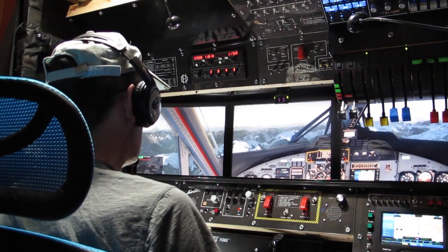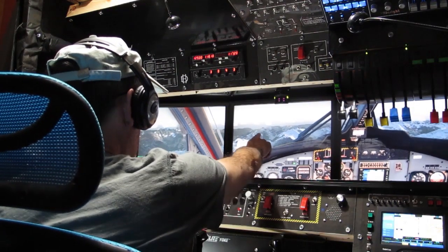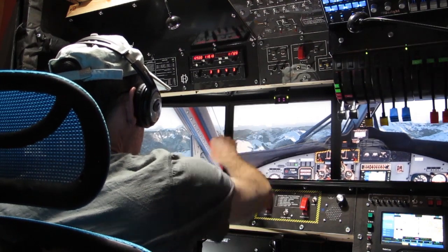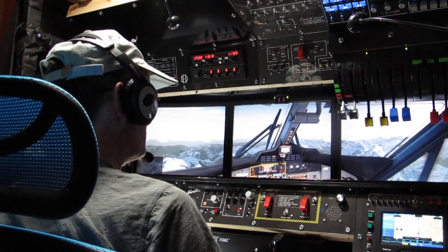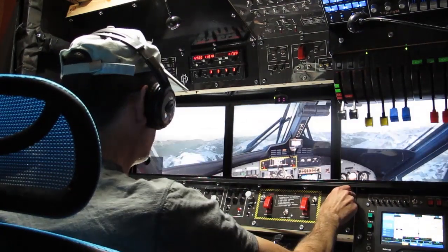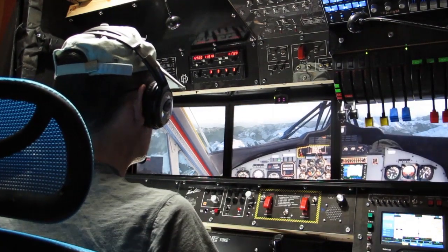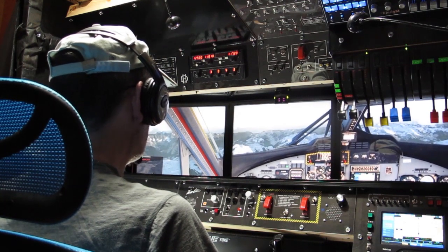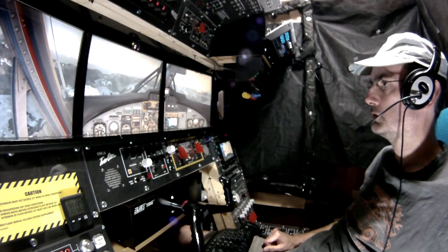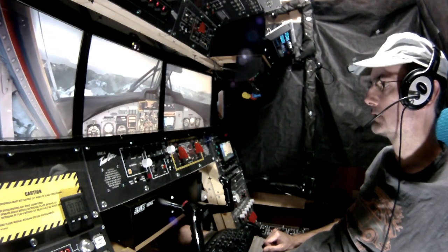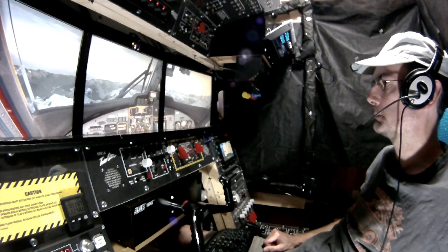Oh, we can see Martin's Bay actually, you can just see the shoreline in the distance there, and definitely no cloud cover there, so we shouldn't have a problem. The other function of the altitude alerter, if we can connect it to the autopilot, as we've seen, is that we can get it to fly to an altitude and then dial in altitude hold for us. So we can do that on the way up.